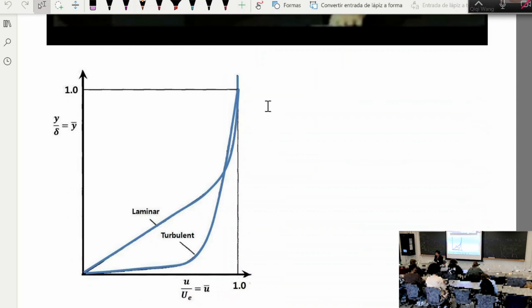Okay, so before I show you the figure, I show you the video. I'm basically drawing the most iconic difference between a laminar and a turbulent boundary layer. So for a laminar boundary layer, it looks more like this. This is actually the Blasius boundary layer plot. You're going to see inside the boundary layer, there is a large region where the velocity gradient looks almost the same. I mean, actually they are not. The velocity gradient always decreases as you go towards outside, but the rate of decrease, the amount of velocity gradient, is pretty constant over a big portion of the boundary layer.